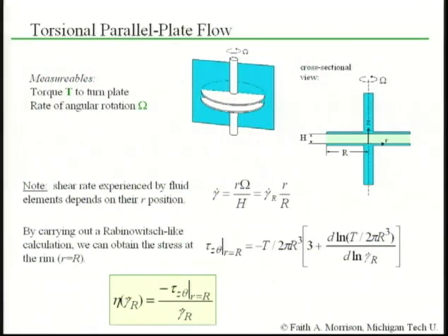is a strain inhomogeneity. So for instance, if you think about the ice skater problem, if you're turning a flow like this, the material elements near the center for one revolution travel a much shorter distance than the fluid elements closer to the outer rim. So it's like ice skaters going around in a circle. The one on the outer edge is going the longest distance and really has to work the hardest. So there is a similar strain inhomogeneity problem that's just like in the capillary.